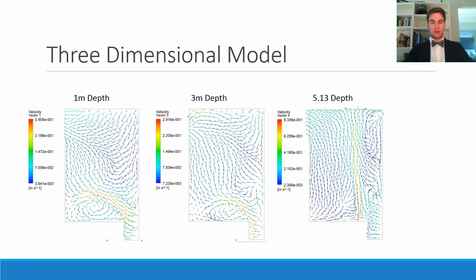Furthermore, the region in the top right-hand corner, where the mixer is located, while still subject to low velocities, has a flow direction that is upwards, and this may assist to keep microorganisms suspended. This, however, is due to the flow from the A-recycle pump. From the velocity vectors, the region in front of A-recycle pump 3 may accumulate sediment, and this is better illustrated from the velocity vectors in the YZ plane.